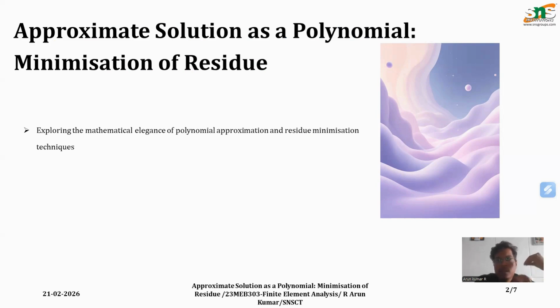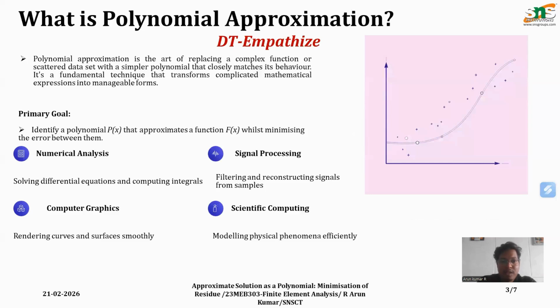First of all, we have to assume a polynomial function for the respective type of beam. Then we substitute the unknown coefficients A1 and A2. Then we want to find where the maximum load and deflection are, and we want to calculate the deflection of the respective beam.